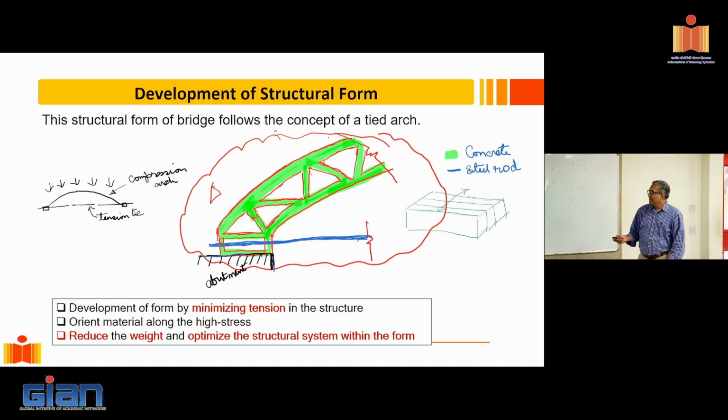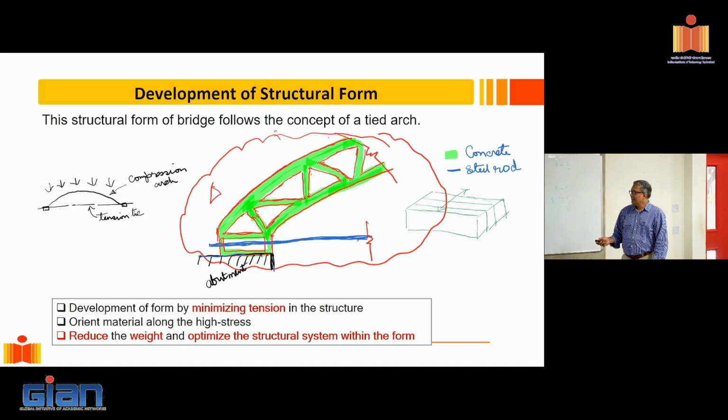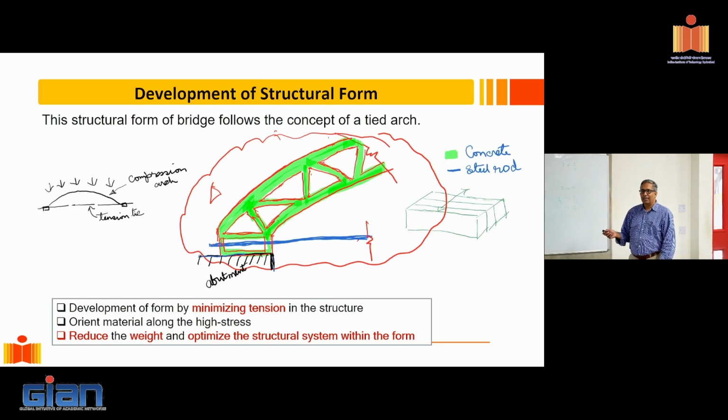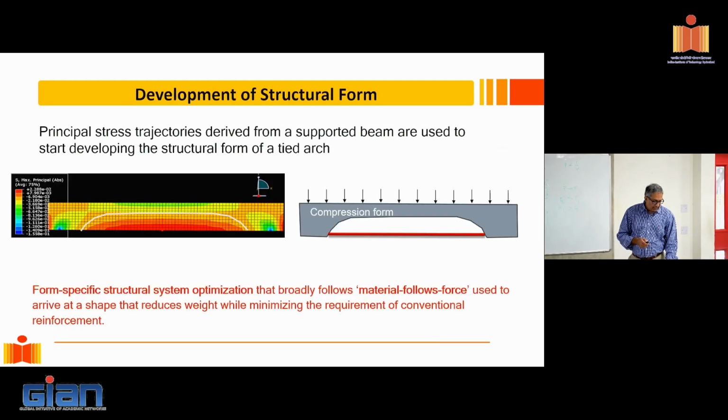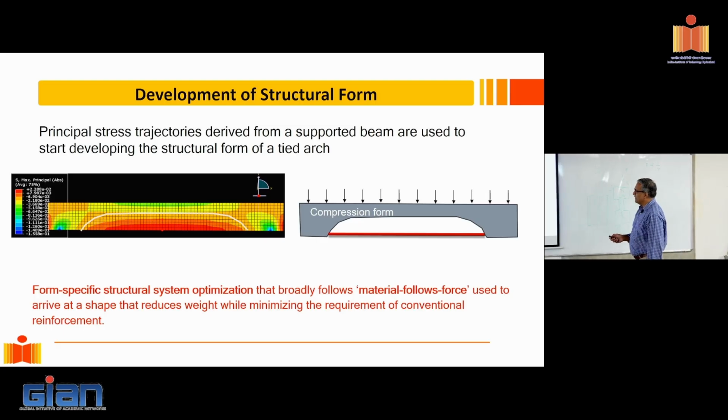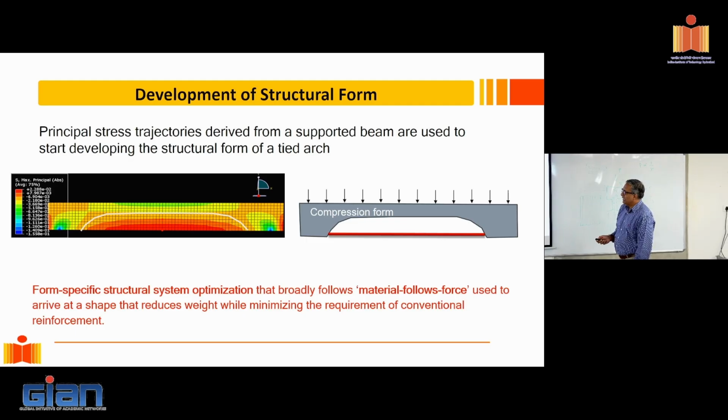But the problem is, if I give you a bridge like this, the riding surface becomes curved. Now it's like climbing a mountain and coming down. That's not exactly friendly. So then we said, okay, let's exploit this feature further. Go with a beam. So if you look at a beam and you subject it to a UDL, what you'd see is that the top part of it goes into compression, and these darker shades here, reddish and the orange shades, are tension. Bottom is essentially all in tension.